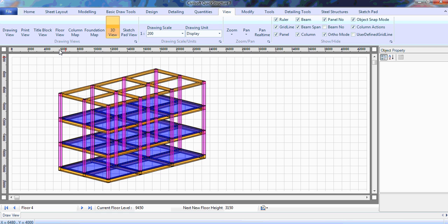So you can see from what I have done, originally I set out to create the ground floor, and after creating it, assuming that the beam arrangement is the same for the first floor, the second floor, and the roof level, I used the ground floor, copied multiple floors, and created my first floor, my second floor, and the roof level. That is how easily you can build an arrangement with the software.